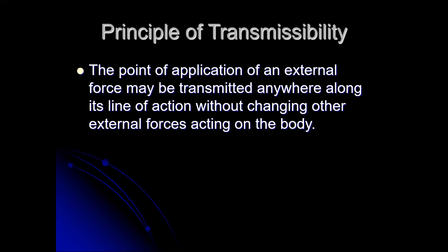As long as you move that force so it doesn't change its angle, it stays on its line of action, and you don't change how much force is involved. So that helps us to simplify how we draw our force diagrams and our free body diagrams. For example, it's a lot easier to draw all of our systems as if all of our forces are pulling on an object. That's not always the case.